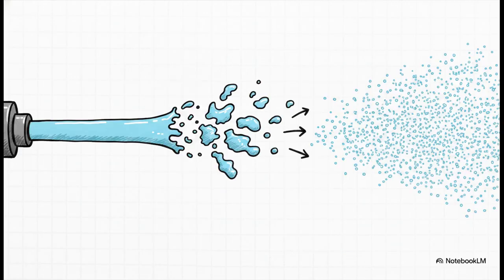Finally, there's this incredibly powerful hybrid trick for simulating things like fuel injectors, where a massive liquid spray violently breaks apart into microscopic droplets. Tracking every single tiny droplet with VOF would completely crash the system. So modern software uses the VOF to DPM transition. As droplets get too tiny for the VOF mesh to resolve efficiently, the software automatically converts them into discrete phase model particles. It seamlessly switches to tracking their behavior as points in space, maintaining physical accuracy without frying the computer.